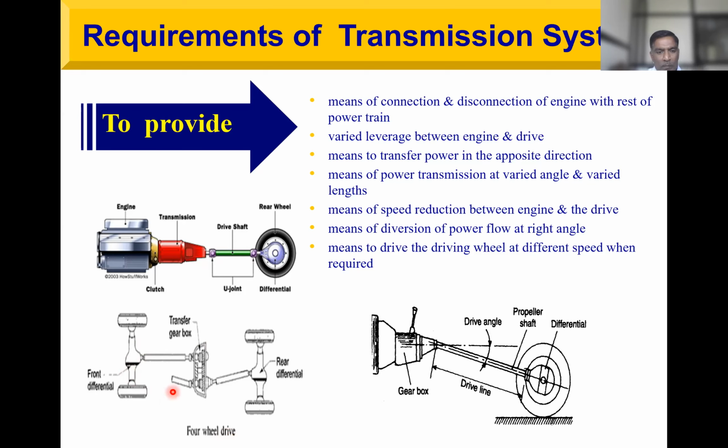So here you can imagine engine power is flowing in this direction and to this rear differential. And now we need to provide power in opposite direction, and that is for this front differential. How to provide that? By using such transfer case.